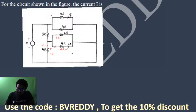Yes. This current is 1 ampere. This current is 3. Now how much is this current? 3 plus 1, 4 amperes. Means this voltage will be 12R. Now this is 12R, and here this voltage is 4R, means this voltage must be 8R. Now this voltage is also 8R, that means I is equal to 4 amperes, isn't it?